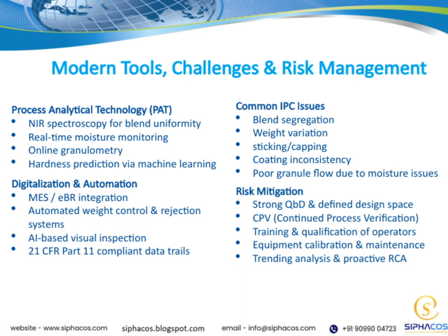We also leverage process analytical technology, or PAT, for real-time insights, using tools like NIR spectroscopy to monitor blend uniformity and real-time moisture monitoring to prevent moisture-related flow issues. Online granulometry helps us ensure particle size consistency, and hardness prediction via machine learning offers predictive insights into tablet quality.